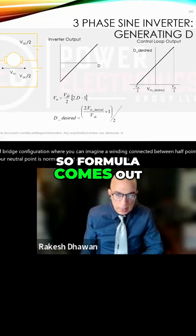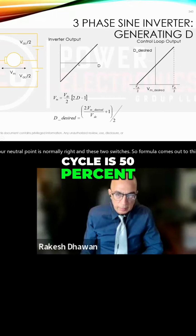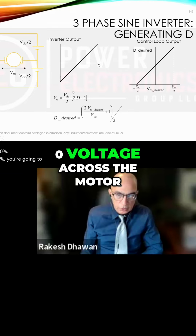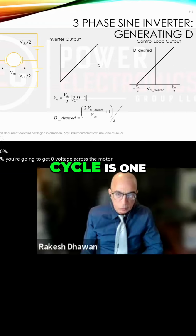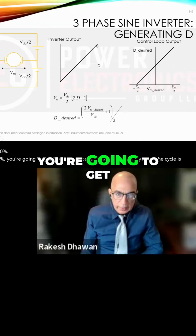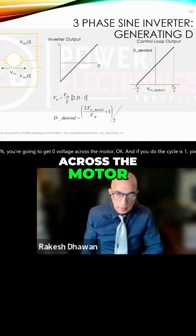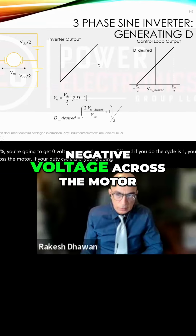So the formula comes out this way, where if your duty cycle is 50%, you're going to get zero voltage across the motor, okay? And if your duty cycle is 1, you're going to get VDC by 2 voltage across the motor. If your duty cycle is 0, you're going to get negative voltage across the motor.